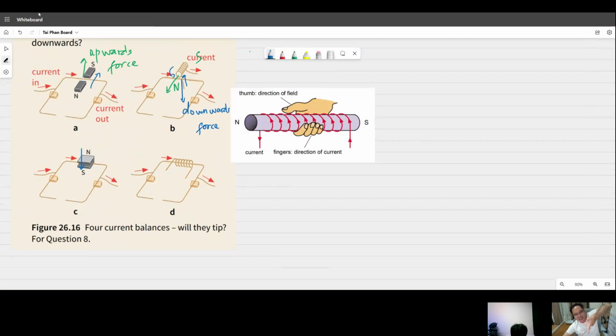See? So difficult. Go with the right hand. There's another way called the right hand rule, which is different from the left hand rule. For the left hand, you have the order F for the thumb, B, I for the first and second fingers: F, B, I. But if you use the right hand, the order is different: I, B, F. I here is thumb, B, F. F, B, I for left hand, I, B, F for right hand.